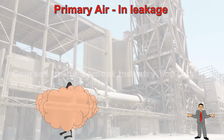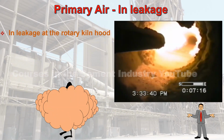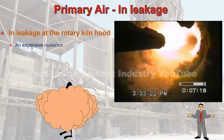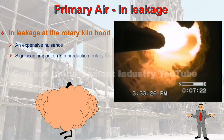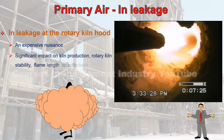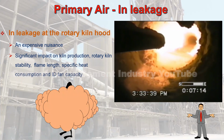Primary air in leakage. In leakage at the rotary kiln hood. 1. An expensive nuisance. 2. Significant impact on rotary kiln production, rotary kiln stability, flame length, specific heat consumption and ID fan capacity.